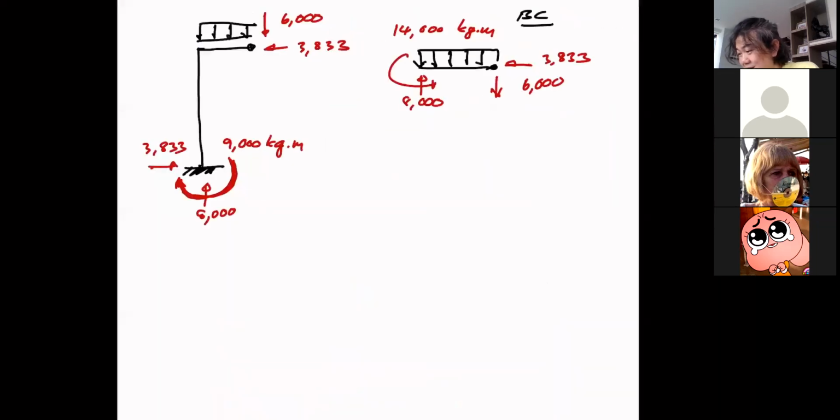Okay, and now when you look at the shear force diagram, if you start from the left, it becomes the upward force now. So this time, we have the positive shear instead, and going down by the uniform load until we have 6,000 here. So that's 6,000. So this area is positive. Shear force diagram in kilogram force.